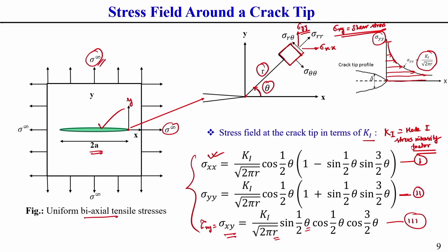That is why we will consider this K1 in this whole LEFM approach. Keep this in mind: opening mode is the most critical crack propagation and crack initiation mode.